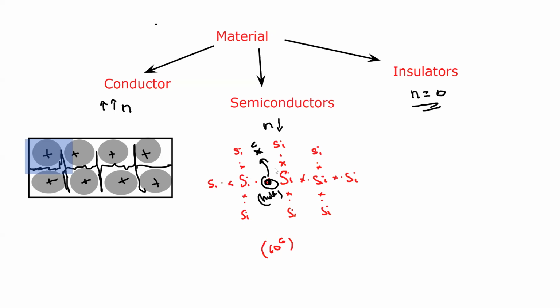What is the advantage of these holes? Holes are actually spaces where the electrons can jump from one point to another. So in a semiconductor with a giant structure, out of 1 million, one electron jumps out from the bonding and starts to move within the structure. When it starts to move, the material starts to conduct electricity. But the conduction will be very low. If I take 1 meter square or 1 centimeter square of area, I will get only a few charges. That's why we say the value of N is very low. Is it clear? This concept of the semiconductor and why low conduction?